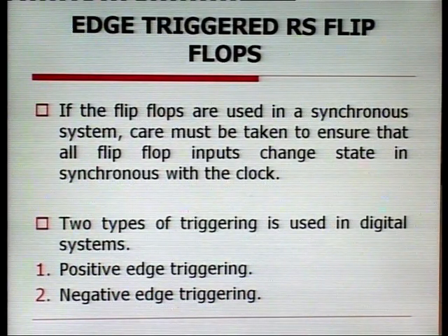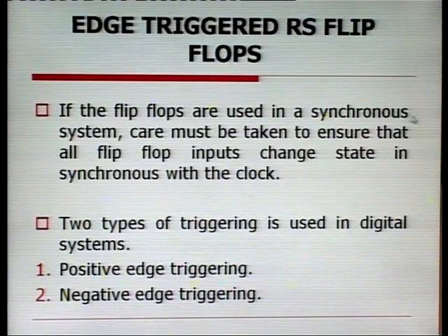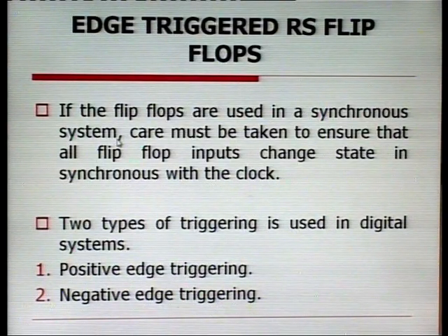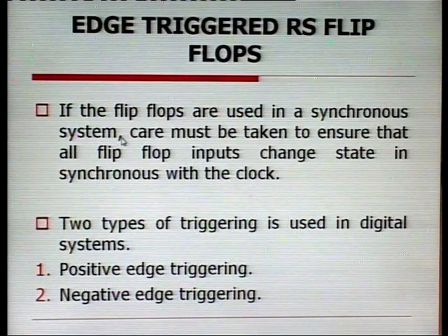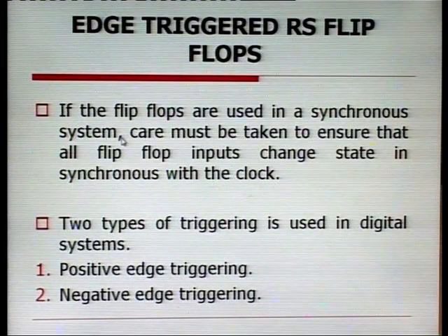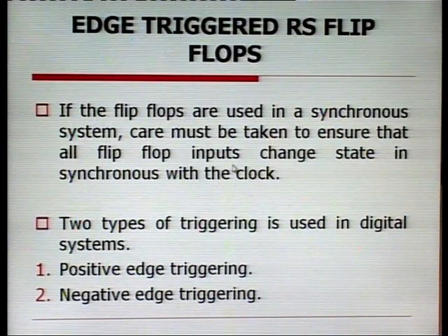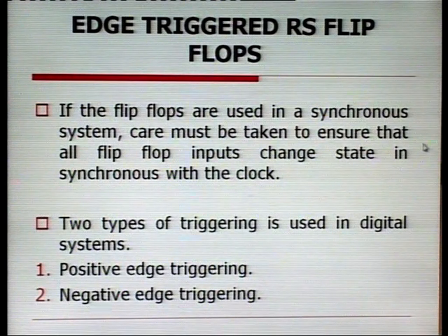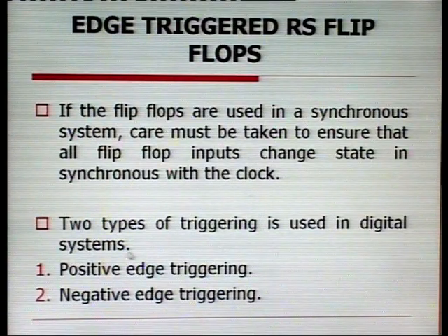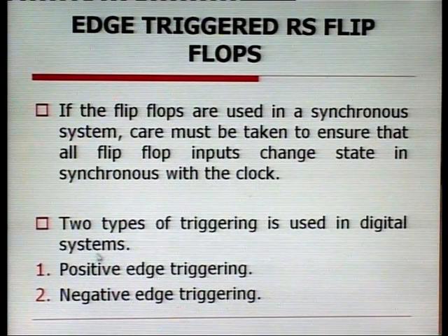If flip flops are used in a synchronous system, all digital circuits are synchronous because they are doing operations with respect to the clock. In that case, care must be taken to ensure that all flip flop inputs change state in synchronism with the clock. Two types of triggering are used in digital systems.